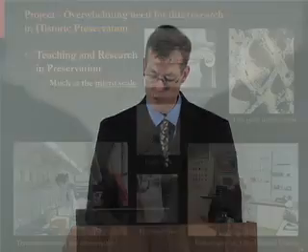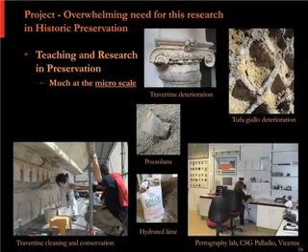At the right, upper and lower photos, that's a medieval tower in Lodi. And it was actually kind of reskinned at a certain point in its life, kind of late Middle Ages, early Renaissance. And you can see this, they're now doing a project to restore the tower. And if you look, you can see the skin separating from the main tower in that photo at the lower right. And by matching up the snapped headers, in other words, the brick that extended back from the new brick into the old brick, you can see how much this has moved. And this has actually moved about 3 inches.